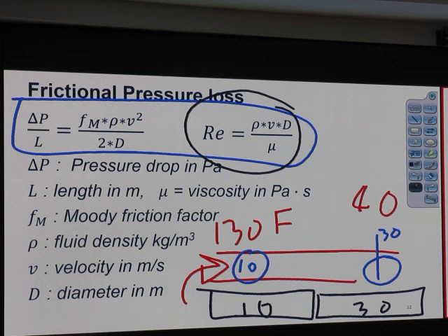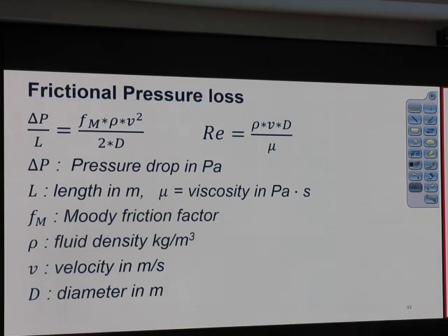Over here it's still available, sir. So this equation can be used for the change of fluid property with respect to pressure. What else can change in terms of fluid property? There could be some phase change, right? When we have the flow, there's a pressure drop. When we have pressure drop, gas can come out of the liquid phase. At the beginning, we may not have multi-phase flow. We may not have two-phase flow. We may just have liquid. But once it flows for a while, there's enough pressure drop that we can have a gas phase coming out.